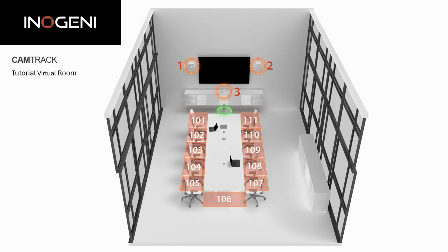The microphone's active zone tells CamTrack which PTZ camera to move to its preset position. Zones can be small meeting corners or large spaces, such as training rooms or classrooms. Each Shure microphone supports up to 8 zones, or even more for the MXA901 and MXA920 microphones that use XYZ coordinates. Each of these zones is linked to a camera preset.